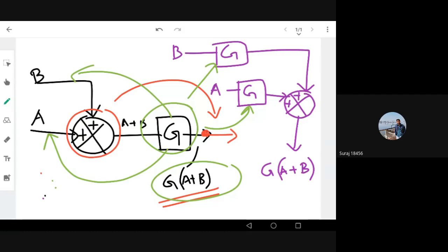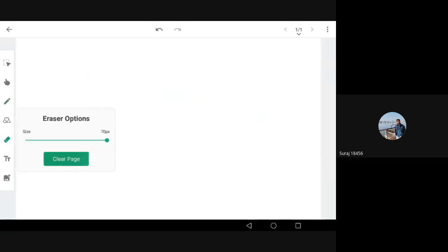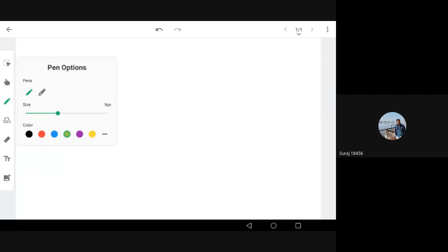Okay. Logically, it is very simple, but you need to use this at the appropriate time. Suppose you are not able to reduce a complicated block diagram, then you have to use this: moving the summing block after the gain block, or the reverse, moving the summing block back of the gain block, etc. So you just need to refresh all those concepts. The same thing I should use when I move the summing point before the block. For example, I have a summing block here.